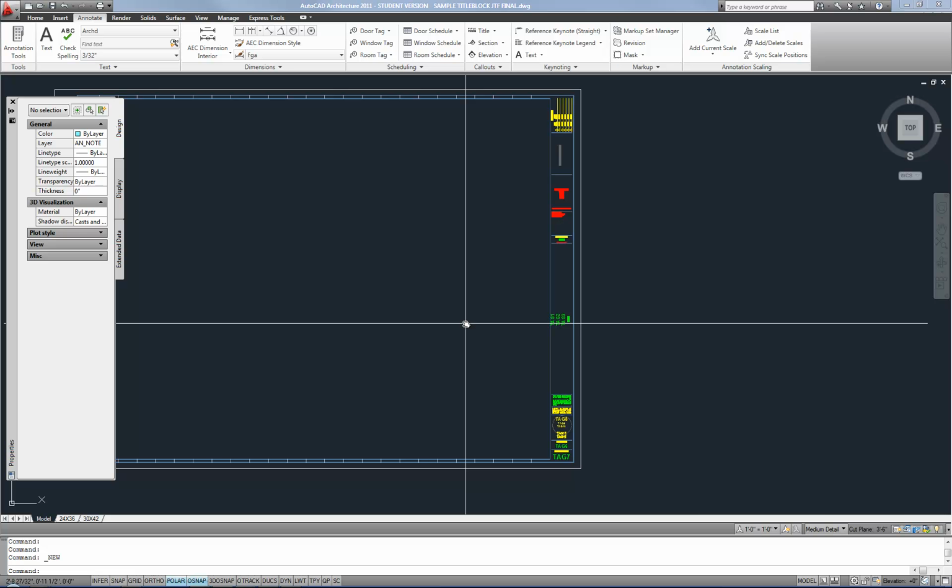So if that's the case, then you would have your title block inserted into model space, update your attributes there, and save that as a master title block, which is then XREF'd to various paper spaces or layout tabs of other files. Either way, the attributes are necessary in order to update the information in the title block.